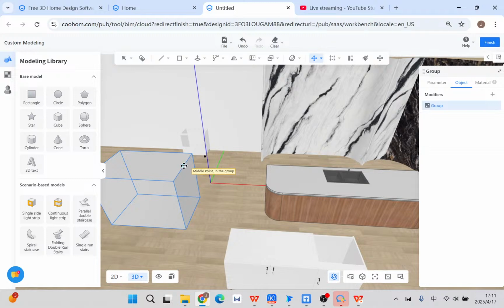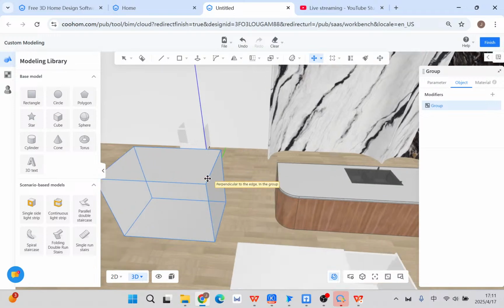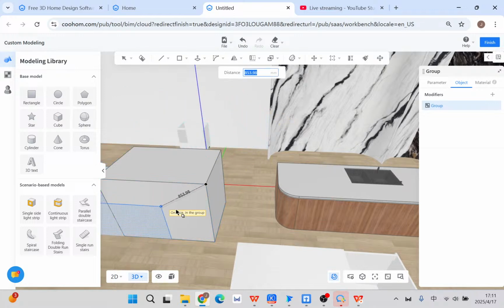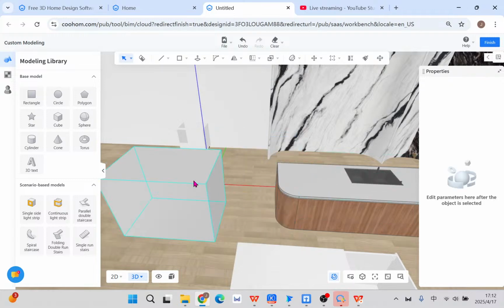But if you use the move, it's hidden away by the mouse, so sometimes it's really hard to see. You see here, when I click, I'm not sure if I have the right position, so sometimes it really causes some mistakes. So try to use the duplicate, the copy. It will be better. At least you can see where your mouse is, if it is touching the endpoint or the position. So just pay attention to this.